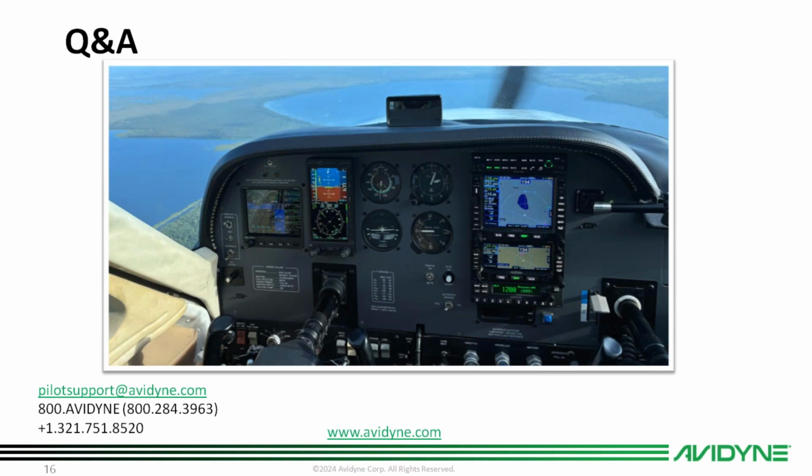So the GFC 500 autopilot is always a hard point that people ask about. The short answer is it does work, but it depends on your installation. It depends if you have a G5 driving it or a GI 275. A lot of the G5 pilots are happy. There have been no reported issues with that. With the GI 275, the only thing that has been reported, which is going to be fixed with the next release